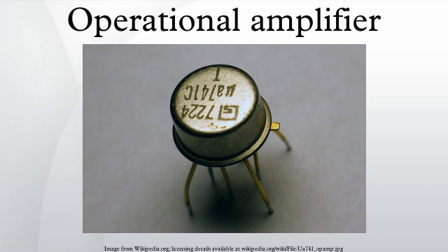This offset voltage can create offsets or drifting in the operational amplifier. It can often be nulled externally. However, many operational amplifiers include offset null or balance pins and some procedure for using them to remove this offset. Some operational amplifiers attempt to nullify this offset automatically.